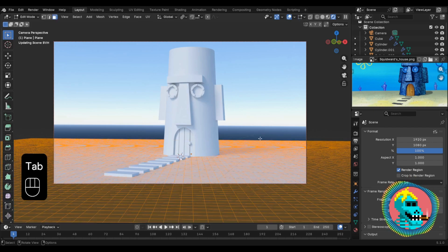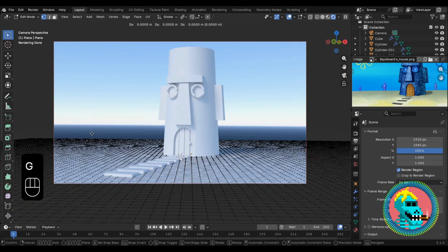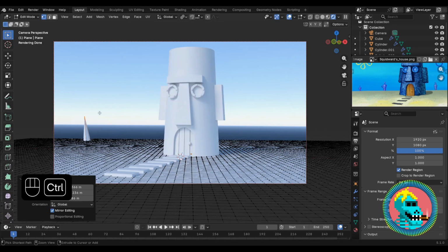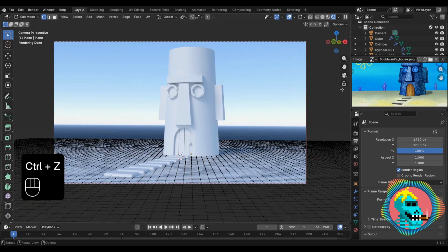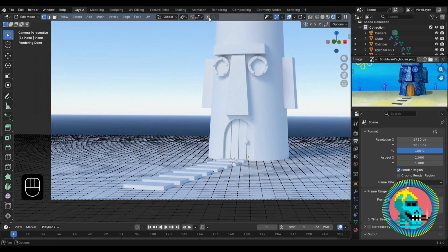Let's go back to setting up our plane. Switch to the edit mode, points mode. Now, if we move one point, we see that we get sharp peaks. And we need smooth hummocks. So we enable this tool, which smoothly pulls other points along with it proportionally.